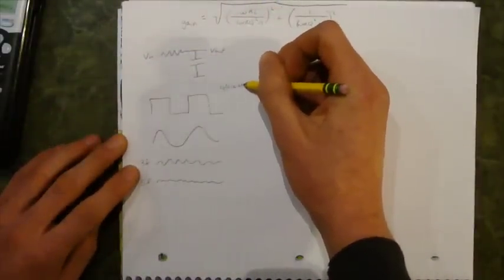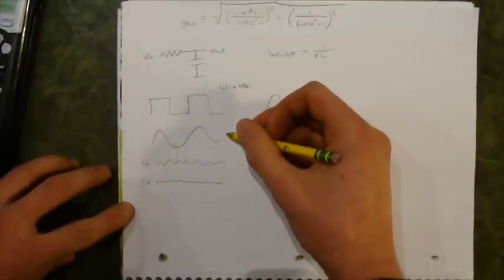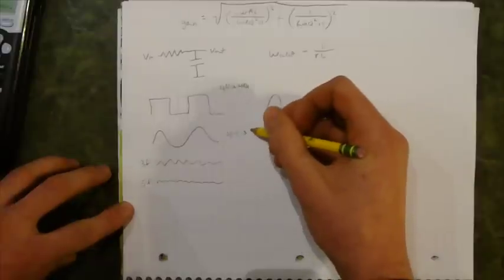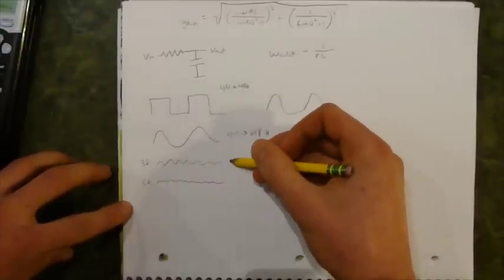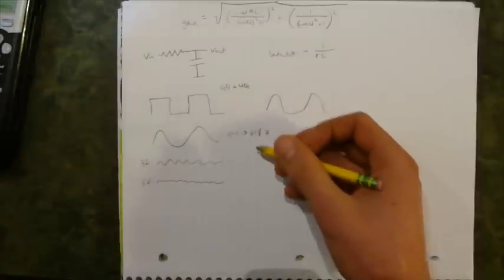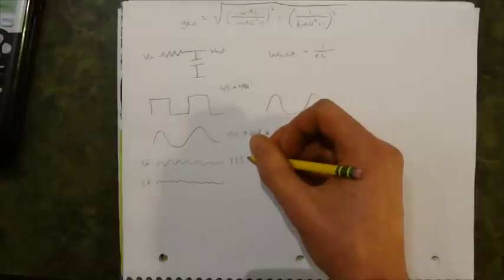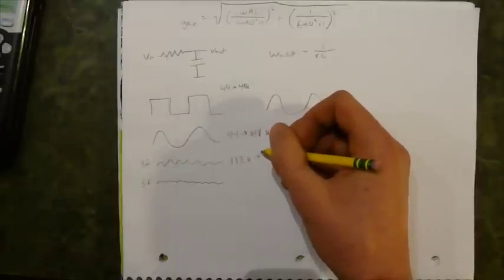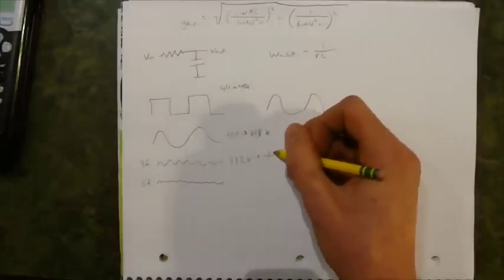48 kilohertz. And our second sine wave, we want it to be 44 to 48 kilohertz. And the next frequency down will be 3 times that, so it'll be 132 kilohertz to 48 times 3, 144 kilohertz. So let's choose a cutoff frequency of 60 kilohertz and see what that does for us.